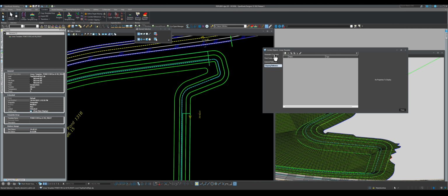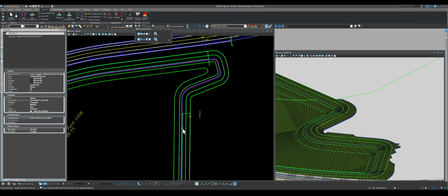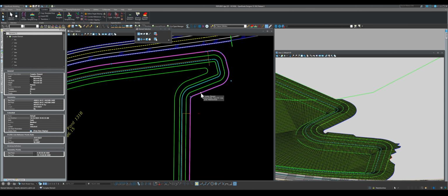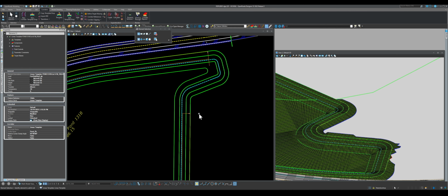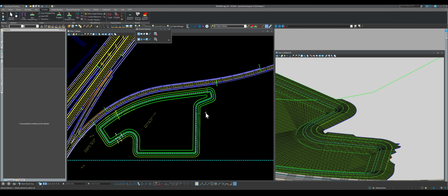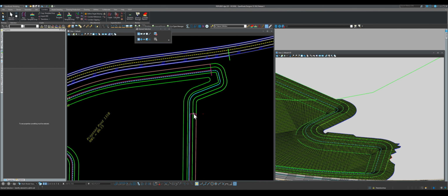And also, you don't even have control over naming the corridor itself. It will take the name of this chain itself that you have, whatever it is. And as you see, let's see what this corridor's name is. Can we? I think we can change it. Can we? Yep, this is the corridor, and you see it's called the linear template. I guess you can change it, for example, to call it pond, whatever it is. But I recommend, let's not use that. Let's use something else instead of just a linear template. Let's use a full corridor.